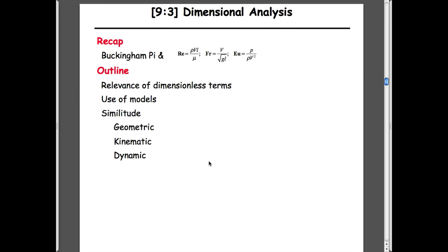So the energy equation was the Bernoulli equation that allowed us to have losses. Another very powerful method in fluid mechanics is dimensional analysis, which relies on defining non-dimensional parameters. And so we can go, well, moderately quickly through this. It's a very simple idea. The idea is that if you take a model and you do an experiment on it at some conditions, you can take the behavior of that model and replicate the behavior of a prototype just from those model measurements.